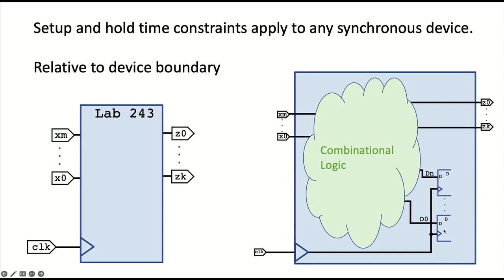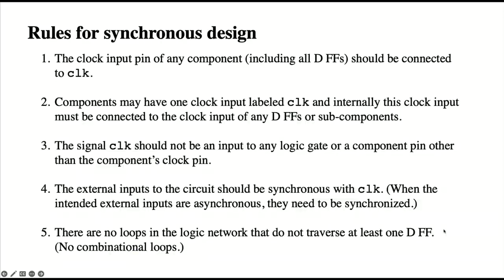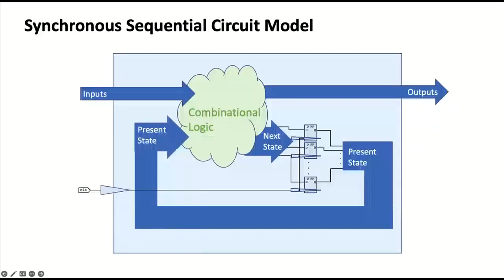So we have our rules from synchronous design, and those are so that we can actually analyze these constraints. That means all of our logic is going to fall into this mode. There are no loops in here. All the loops go through flip-flops and come back. So we can check that we meet the hold time and the setup time.